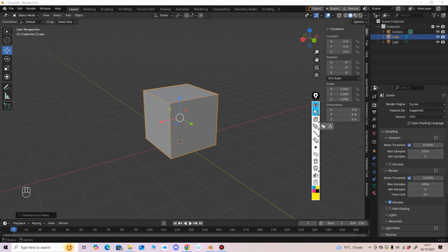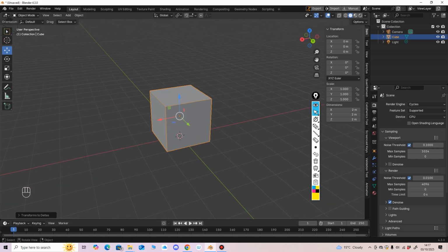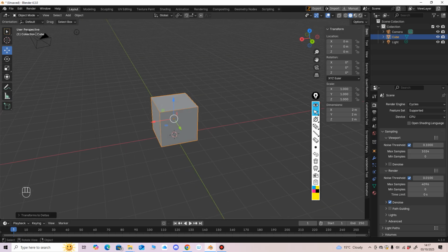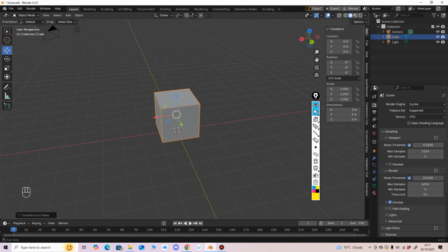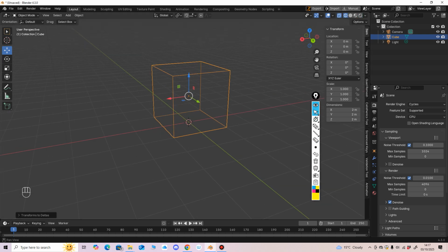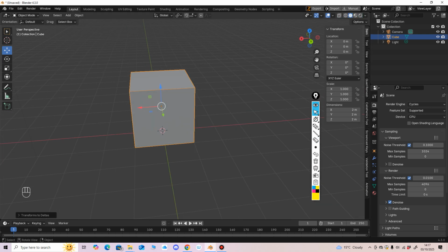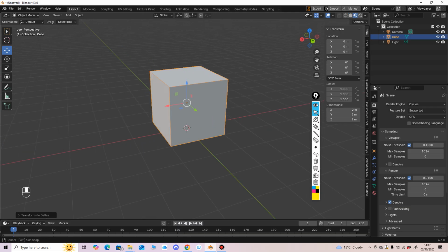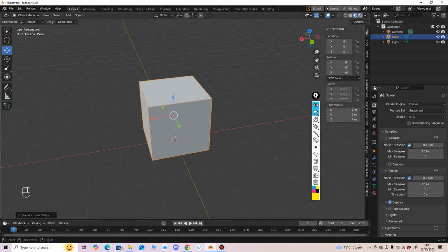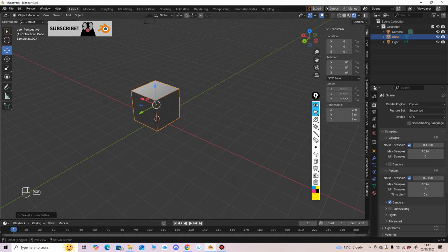And when you're working with lights in Blender, you'll want to switch to your lit mode, which is there on your viewport. So you've got your basic see-through, grayscale, material preview mode, that's fully rendered.